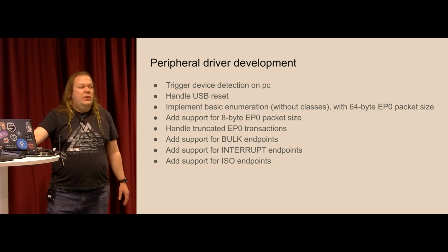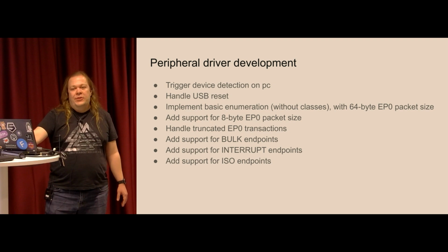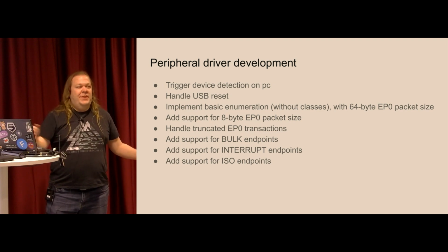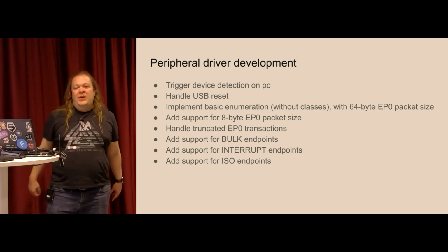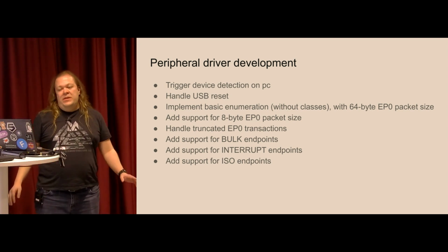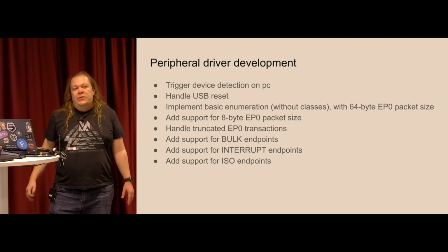Sometimes you may have a board where it is already implemented because you have a pull-up resistor or something like that. So when you just connect your board, the host already tries to detect your device and shows some errors in dmesg, for example. But when you have a normal peripheral, you don't need to do this.